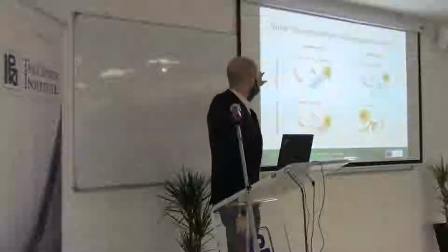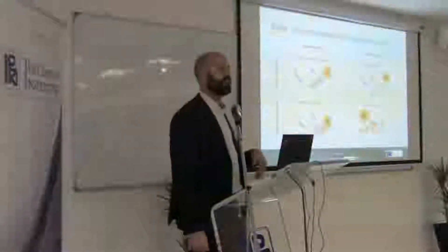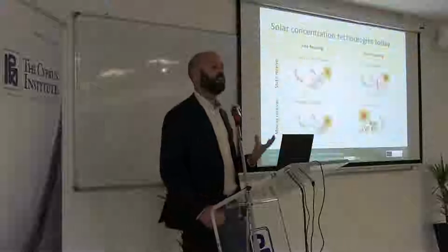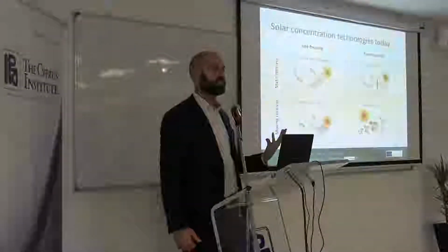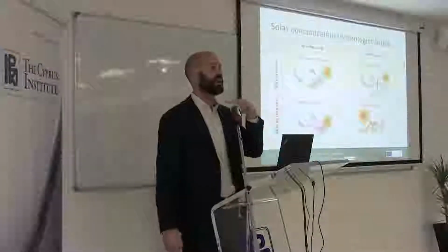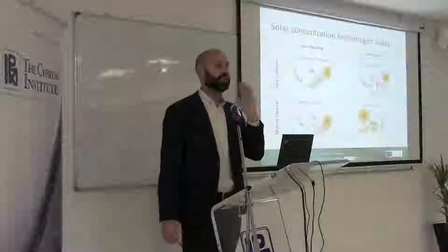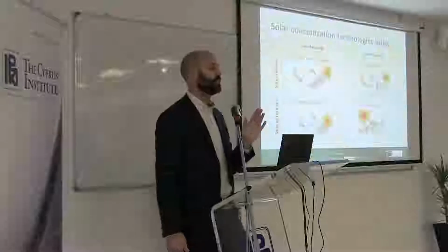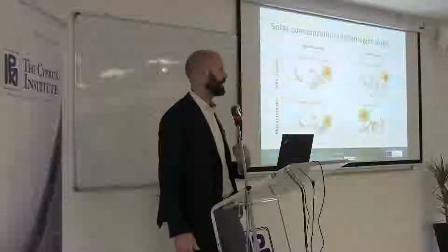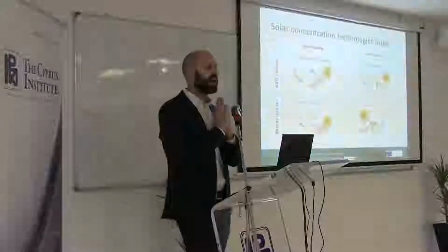And then another way of classifying these concentrating technologies is whether we have a moving receiver or not. As you will see later, concentrated solar thermal systems rely on a tracking system which moves our systems to follow the sun in its apparent motion in the sky during the day. It's very important that our receiver directly faces the sun. We need what is called direct normal irradiation to make these systems work. We cannot rely on reflected or diffused radiation. We need direct radiation from the sun.